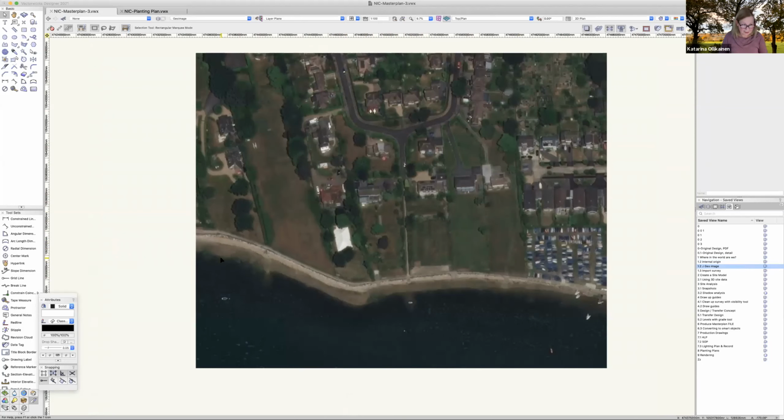The map comes from the GIS tool in the GIS tool set. We have it down here, and it's free to use. You don't need a separate license for this, since it's S3 services and the maps come from S3. By using this GIS link here, you have a whole world in detail mapped out for you in Vectorworks. You never have to make a screenshot of a Google Earth map again to show where your site is located.